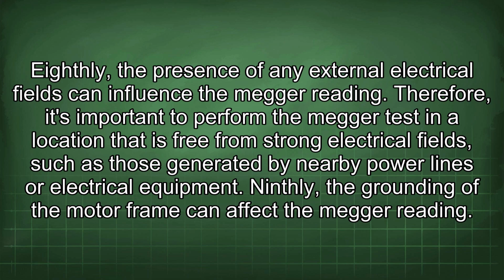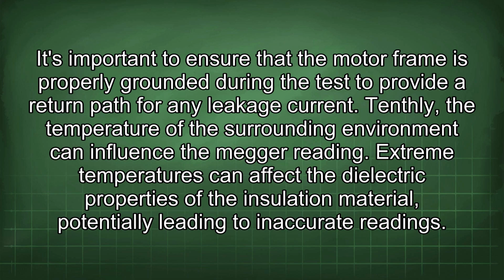Ninthly, the grounding of the motor frame can affect the Megger reading. It's important to ensure that the motor frame is properly grounded during the test to provide a return path for any leakage current. Tenthly, the temperature of the surrounding environment can influence the Megger reading.